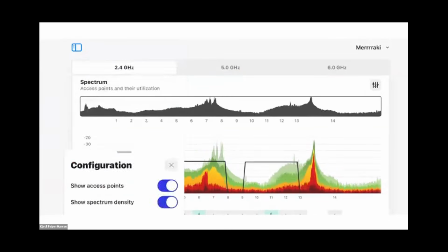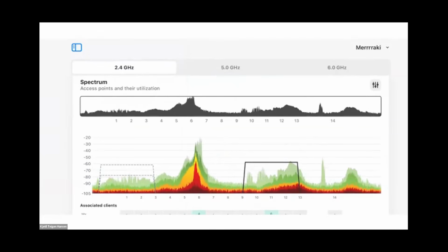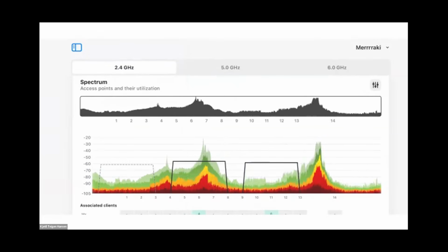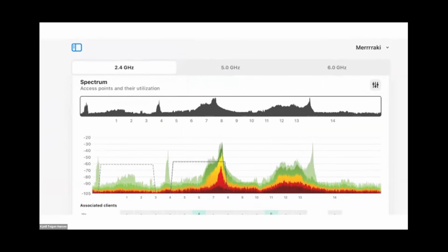Yeah, I think it's also close, but once you get close, you may as well just go by where it's hotter. Exactly. I agree. And without the external antenna, the NetAlly NXT is more sensitive on the back side, at least for my measurements. So if you just turn it around, you get almost 5, 6, 8, 9, 10 dB more sensitive.